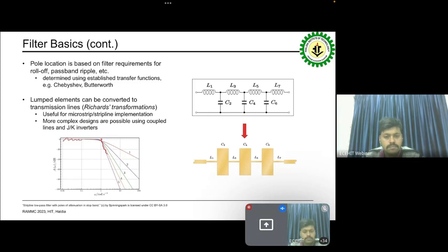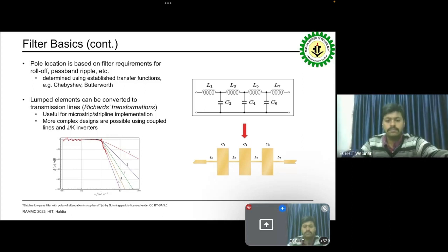Once we generate those lumped element models, they can then be converted over to transmission lines. Most of our devices are going to be microstrip based. We don't do a lot of strip line. A lot of that is usually present in the PCBs. We do some work with planar waveguides, which still unfortunately utilize a lot of microstrip and coplanar waveguide topologies that still need to be modeled. So we're still looking for a lot of the parasitics, the inductance and capacitance that's generated, especially at high frequency, where you see that massive change in impedance. And there's also more losses associated with a lot of that as well. So even though we may be developing planar waveguide technology, we're still having to integrate a lot of those lossy components into that waveguide architecture without using some more advanced transition means to get into the waveguide.